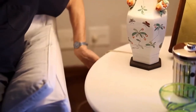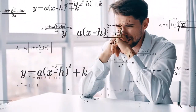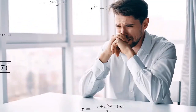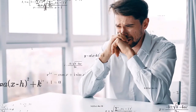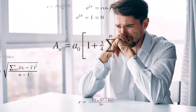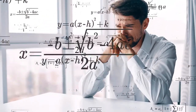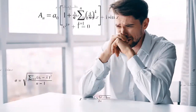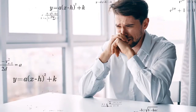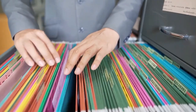Now imagine that the customer wants to have a light switch so they don't have to plug and unplug the cable whenever they need the light. On average, let's say that customers will press the switch 10 times a day. They're expecting to use the desk lamp for at least 2 years. So, you must make sure that your switch, on average, can be actuated 7,000 times without failure. Moving forward, your customers could have color preferences, shape preferences, additional functions like adjustable height, etc. The list of requirements could go on infinitely. In order to develop and introduce a sellable product, all of the main requirements should be met and adequately addressed.